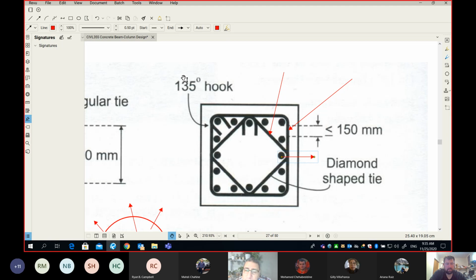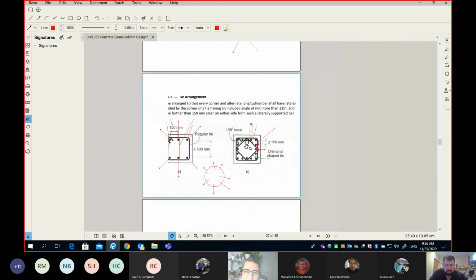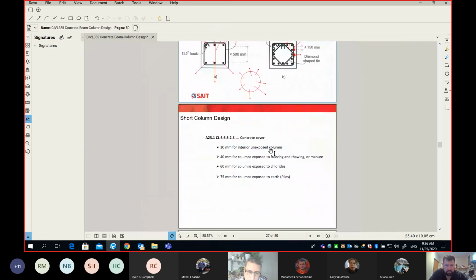It became supported. And now what I can do is I can go and ask myself, now let's go from here to this guy. As long as this distance is less than 150, it means we're okay. It means we don't have to add anything to those unsupported bars, because simply the tie is short enough and strong enough. Okay, hopefully this convinces you, and we will have a numerical example later on.